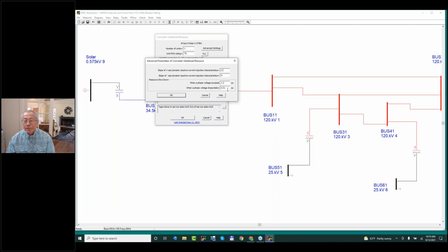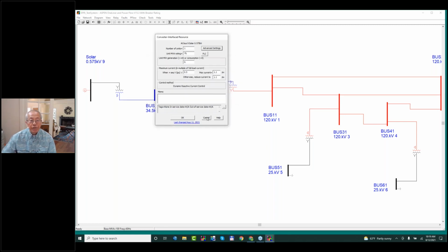Okay, so that points out that if you want to test these things, it's best to put some kind of 1 ohm or 2 ohms of resistance to the fault. Otherwise, you're not going to see any output at all. Okay, so let me go ahead with all that.